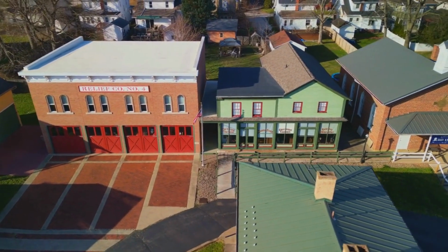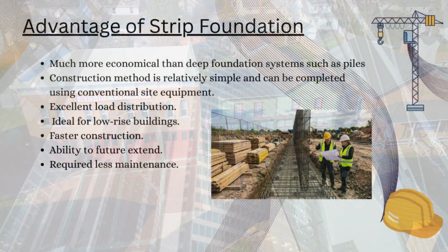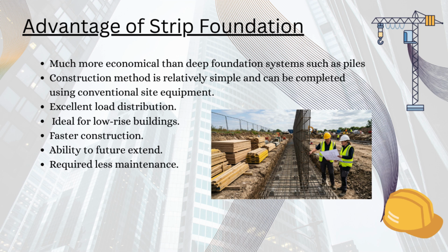Now let's look at the advantages of strip foundations. First, they are much more economical than deep foundation systems such as piles, because they require less excavation and no specialized construction equipment. Second, the construction method is relatively simple and can be completed using conventional site equipment.